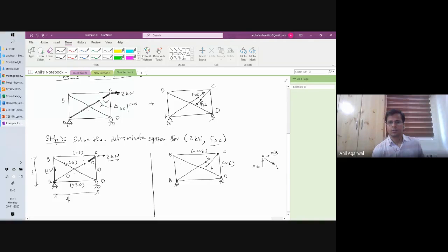So you get positive 1 tension in the diagonal member, that is BD force, and in member BA you get compression of 0.6. Okay. Coming back to joint, again joint A will not give you much information. Joint D, because right now we are not interested in calculating the reactions, we are mainly interested in calculating the member forces, internal forces. Joint D, we have a compression here, that means it is being pushed by 0.6 here.